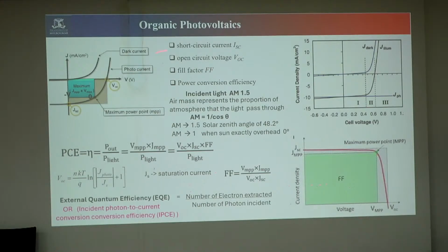So here this is the short circuit current and this is VOC, and the fill factor: normally we get this type of exponential curve. We ideally want it to be flat and then suddenly drop. We need something square. Normally we don't get that. If it is square like this, the fill factor will be high. Fill factor is how square the curve is. If it is highly square, the fill factor will be high. If it is like this, the fill factor will be low.